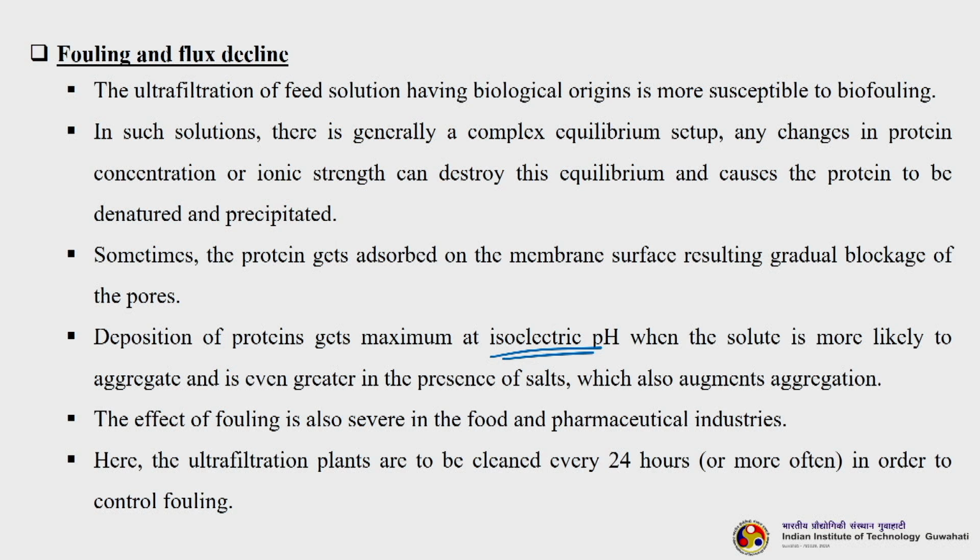So, the effect of fouling is also severe in the food and pharmaceutical industries. Here the ultrafiltration plants have to be cleaned every 24 hours in order to control fouling. So, frequent cleaning of ultrafiltration systems is required because proteins are more susceptible to fouling.